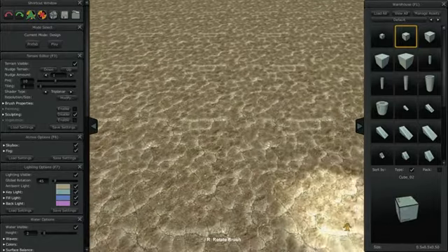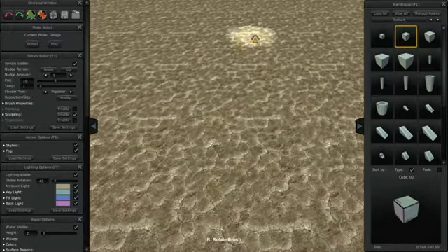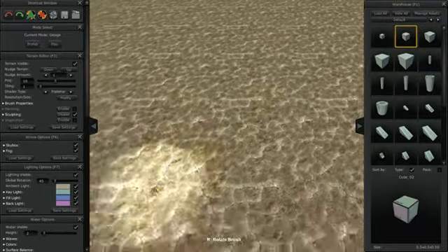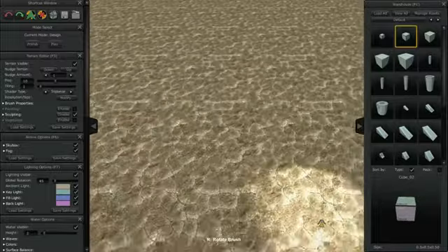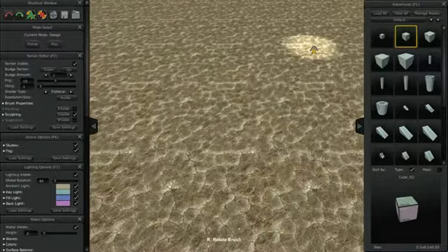Point to a location and press the F button on your keyboard. F meaning focus or frame. The workspace camera will move to that location. Note how the pointed area moves into the center of the viewport.